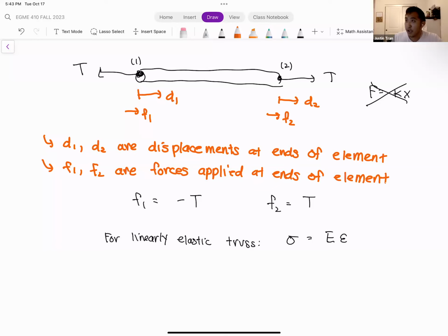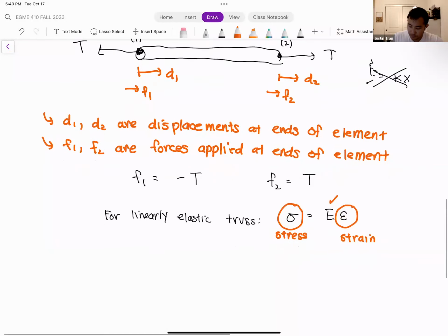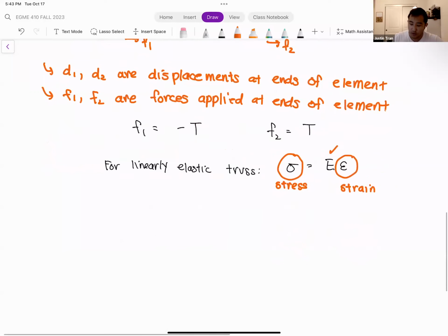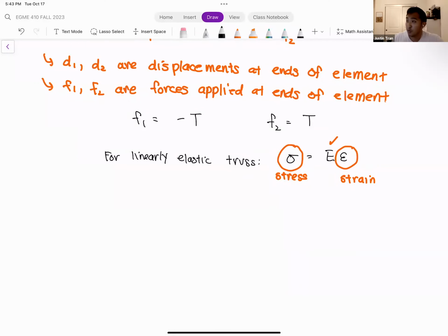And so you can see here we have three elements in this equation. We have the E. We know E already, so that's no surprise, and we can leave that alone. Here we have the stress, that's our sigma, and epsilon here is our strain. Let's represent these using the variables from this figure, and then we can rearrange as needed. Let's do the stress first. We know the stress is nothing more than a force distributed over an area.